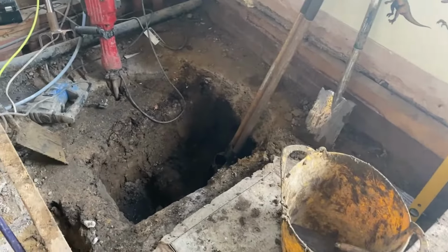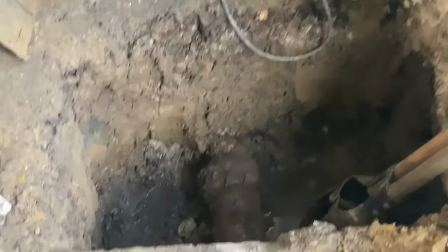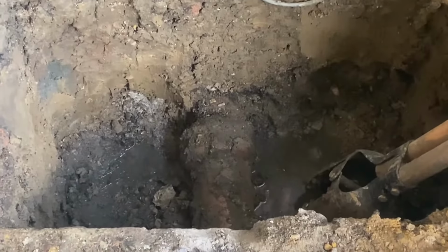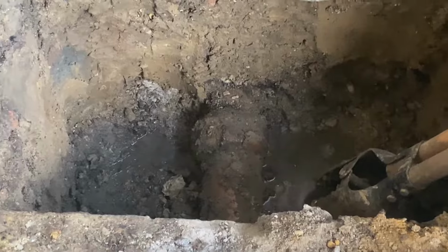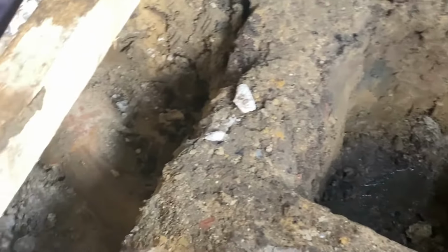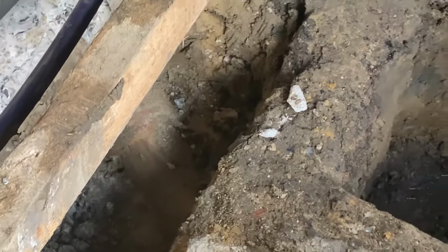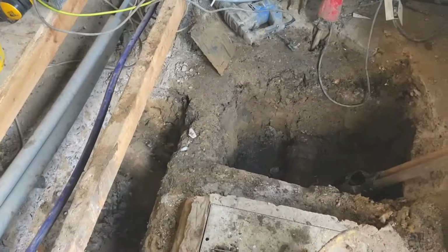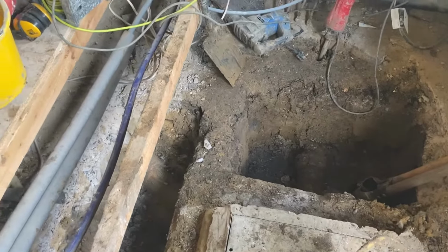So a lot of excavation work. You can just see the start of the sewer pipe there. If you look down, there it is there. So that sewer pipe is running all the way down the road. That's for everybody on this road, all the houses. You just saw in the graphic, I drew that black line. So that's the live pipe. So we need to be careful of that, because if we cause damage to that pipe, then all of the sewage that's coming from the houses above us on the road will start to empty into this hole, and obviously we don't want that.